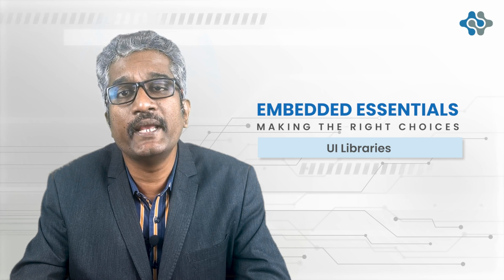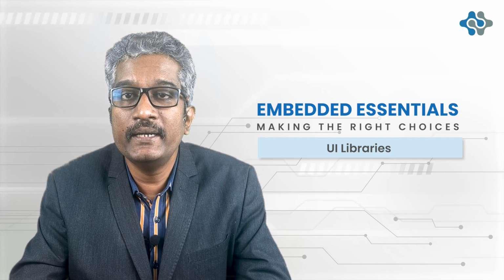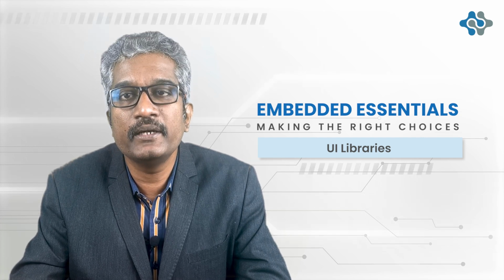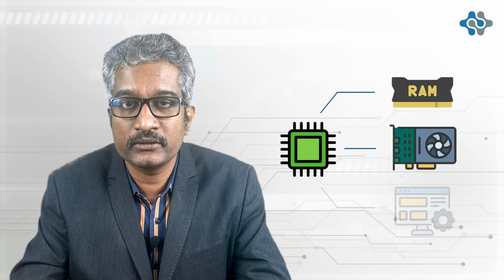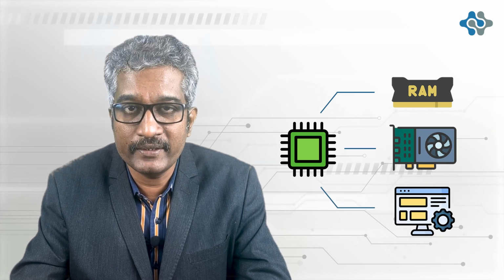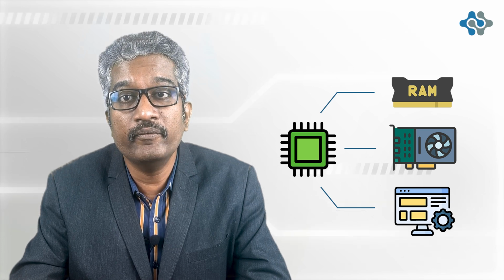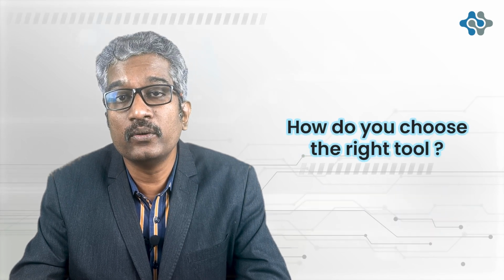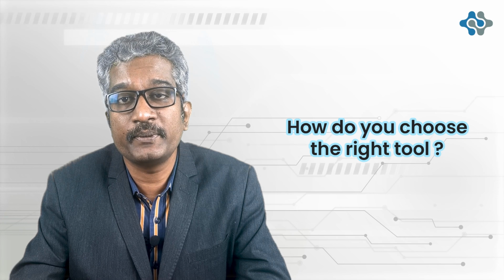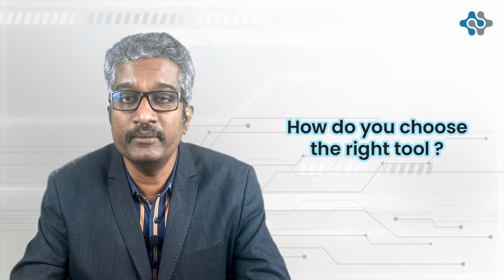Building UIs for embedded systems is fundamentally different from desktop or mobile. We are working with limited CPU power, maybe only a few kilobytes of RAM, a few megabytes of flash, often no GPU or a very basic one, and displays with limited resolution or color depth. Every pixel drawn, every animation frame, every memory allocation counts. So, how do you pick the tool that lets you create a compelling user experience while respecting your hardware's limitations?